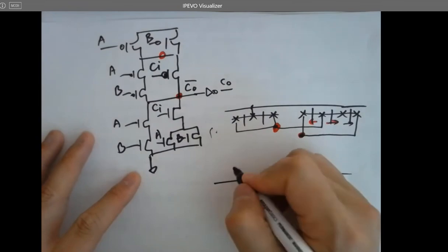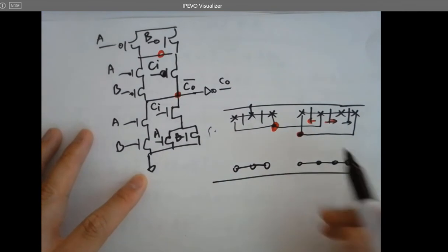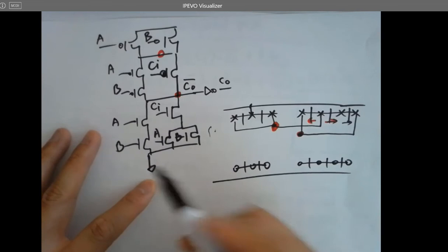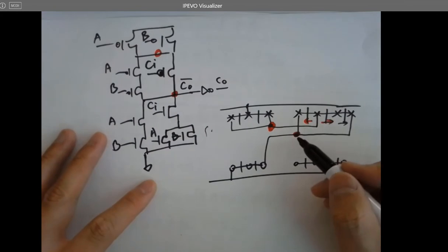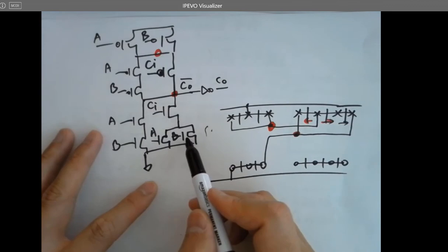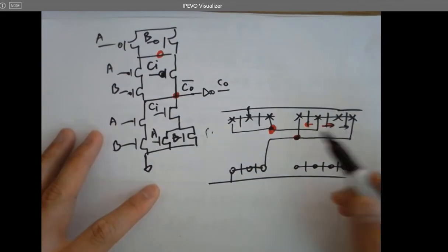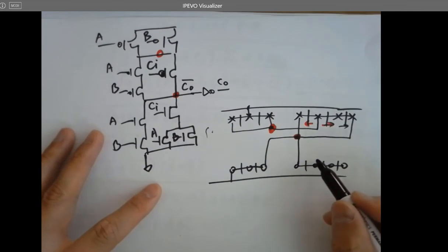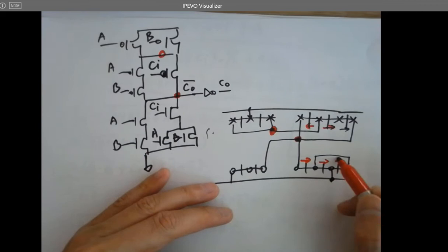Then the NMOSes, first, you got 2 NMOSes in series, and then the same signal, but you have 1 and then 2 in parallel, 1 in series. That's pretty simple. It's pretty much the same structure as here, right? So I just want to directly connect to here. Then it's 1 in series and then 2 in parallel. Right. 1 in series and 2 in parallel.